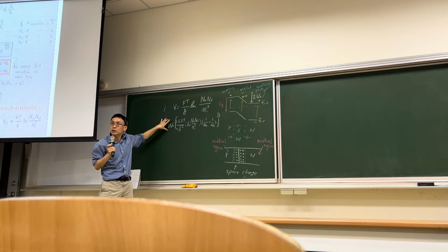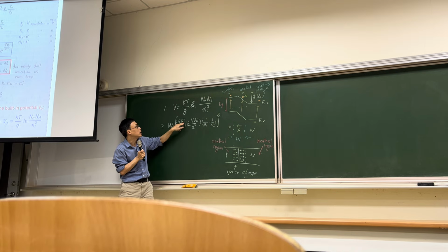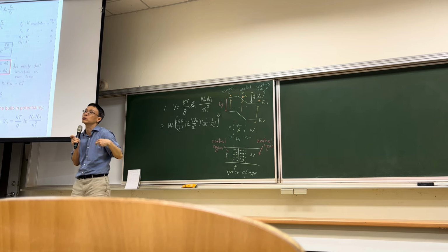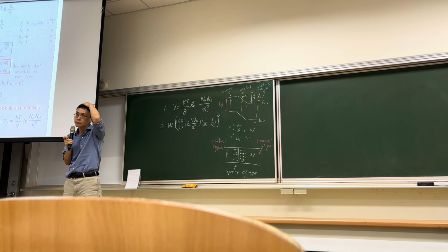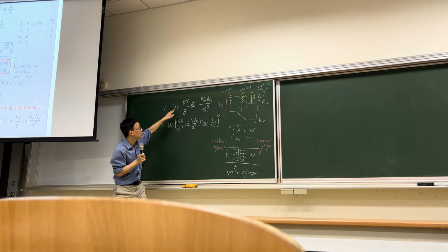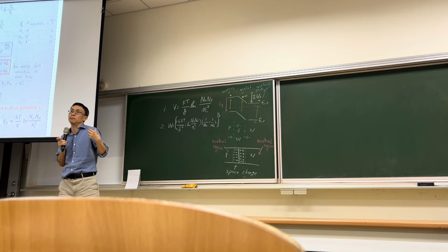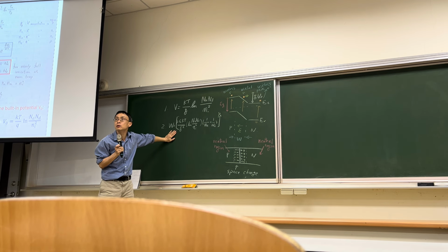And C is also determined by the doping concentration, by the temperature, by the material you choose, right? Ni is the intrinsic concentration, which is determined by the material type, like silicon, gallium nitride, and arsenide, right? And then this is coming from the potential voltage, right? So our next step is to derive this long equation, okay?